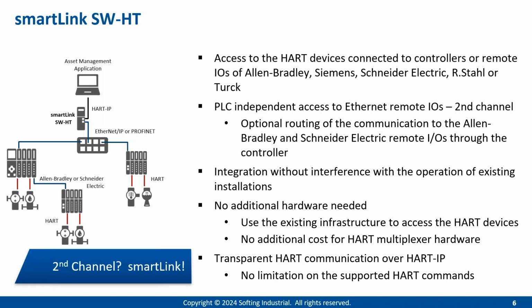As mentioned before, we have the possibility for the asset management application to do a transparent HART communication over HART IP. That's the interface we are providing on the north side with our smartLink SWHT. And that means the application on top has no limitations on the supported HART devices. So any devices you have can be parameterized and monitored.